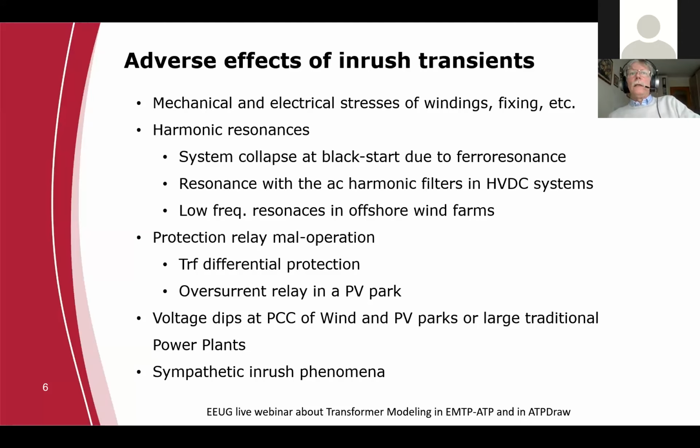We feed the relay protection from the secondary. So if the CT saturates, the protection device will receive something different from a signal proportional to the primary current.